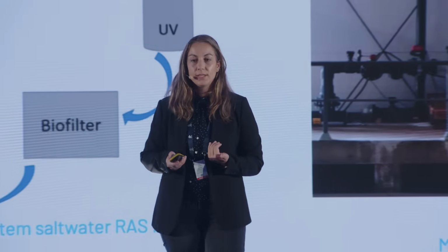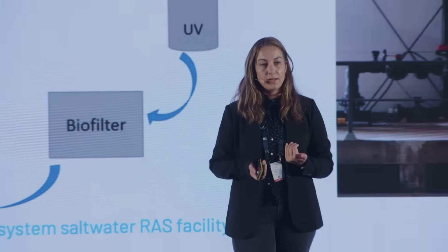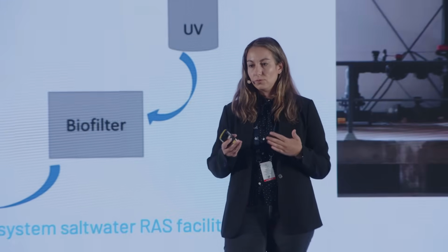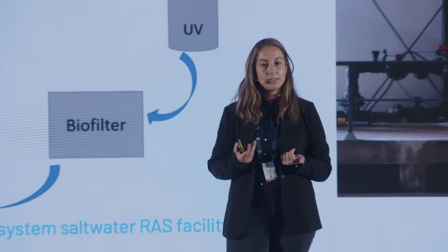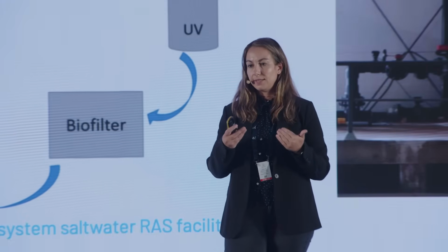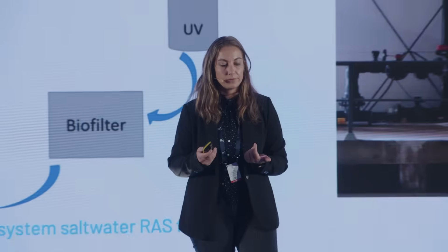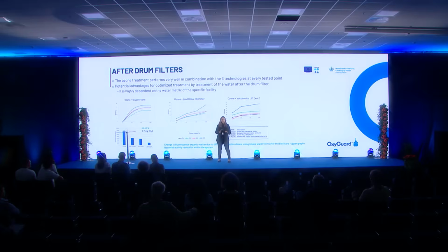In this project, we tried 3 different technologies, the oxygen cone, skimmer, and vacuum air lift, and we tried to compare which is the most efficient to dissolve ozone. We applied 4 different ozone dosages, and all these 3 equipments were placed before and after the drum filters in order to see if the positioning affects the treatment. Our results suggest that all 3 technologies were efficient, and there are some potential gains of placing them after the drum filters.